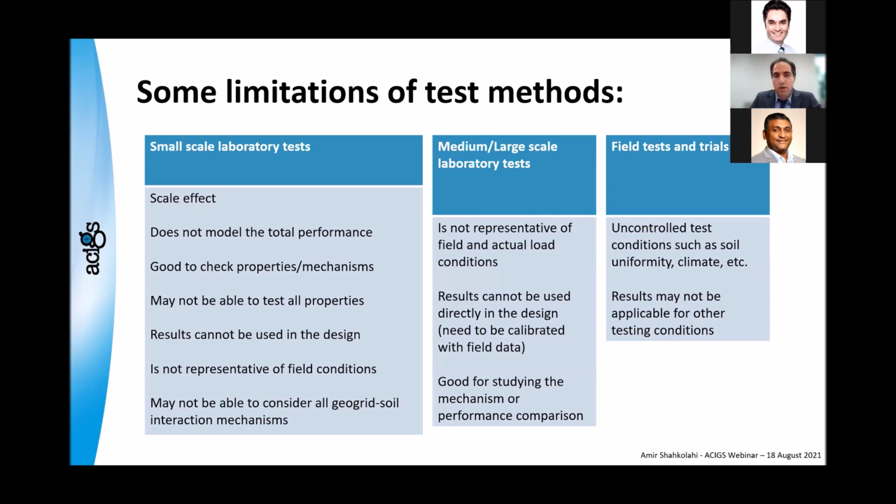What about medium to large scale tests? For example, plate load testing in the lab, or large scale track cell testing. It is not representative of field and actual load. It's good, but it's not exactly actual conditions on the site. Results cannot be used in the design. That's very important. It is not a design test.